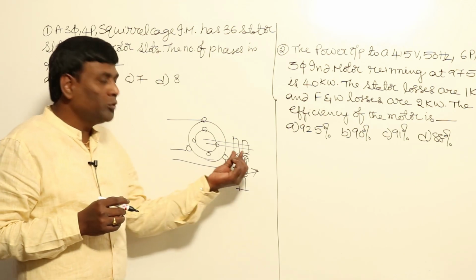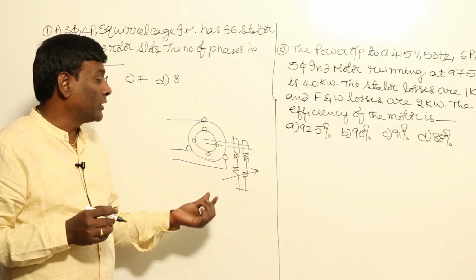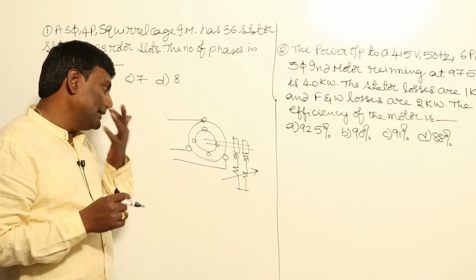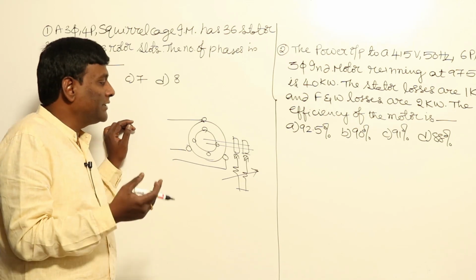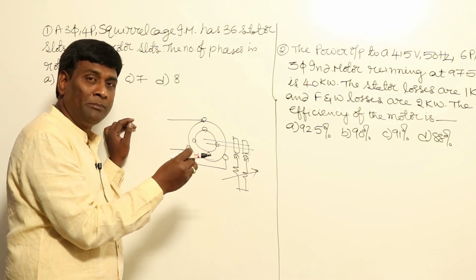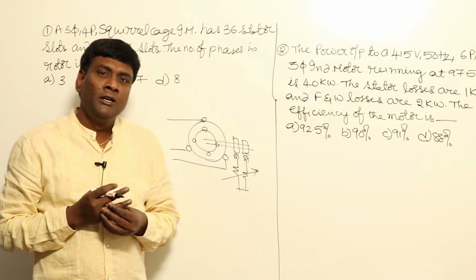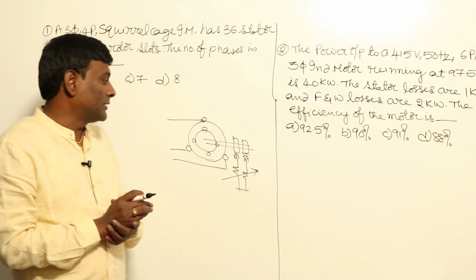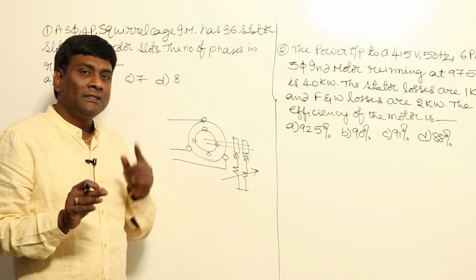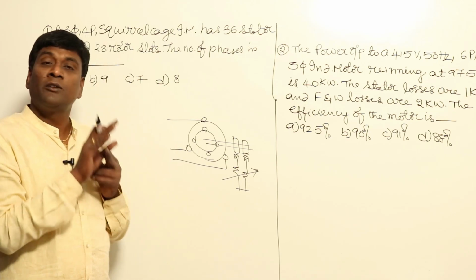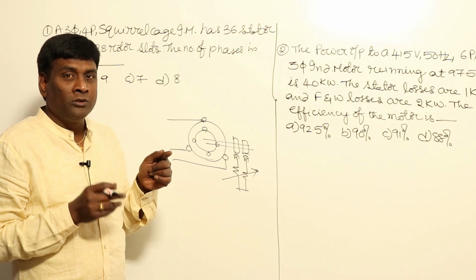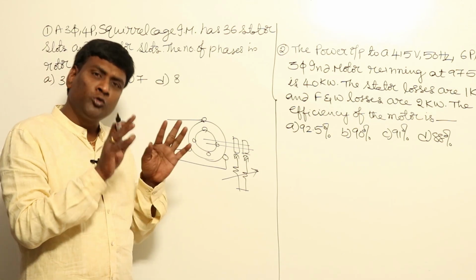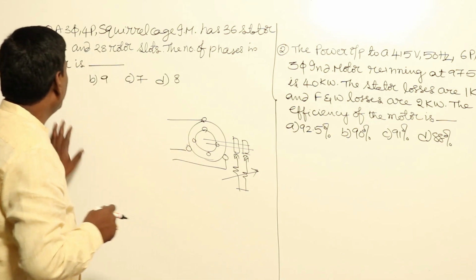In order to avoid 1 slip ring, 1 brush and 1 resistance combination. But recently afterwards, 3-phase load boxes developed, and actually maintaining an extra slip ring doesn't matter much. So that's why we are maintaining 3 slip rings. So the point here is very simple. Stator number of phases and rotor number of phases need not be same. But the number of poles created by stator and rotor should be same.